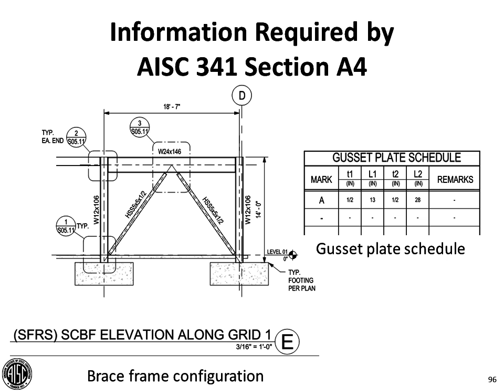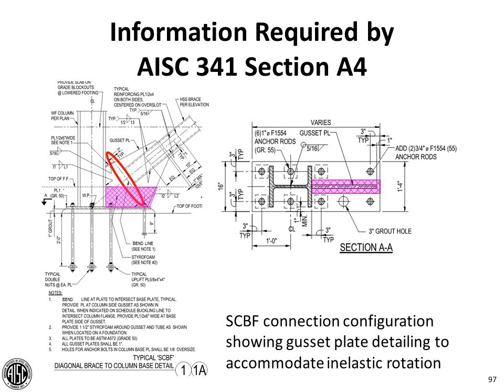In terms of special concentrically braced frames or other brace frames, just show again a typical elevation. This is a nice simple one, only 2 stories or only 1 story tall, and it's simple in the sense that the gusset plate schedule lists again only one particular gusset plate geometry. And then through the use of typical details, the basic geometry of the gusset plate can be understood by the fabricator when they have to construct this detail.